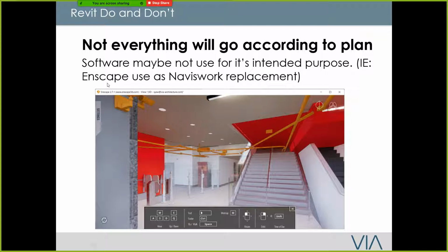So what I find is that you can actually use Enscape, right? Because Enscape is basically you walk into the space and use it as a visual check. What I did here is put all the mechanical under one color and structural another color. When you clash it with architectural, you get this color mash and can tell what's mechanical, what's electrical and what's structural.